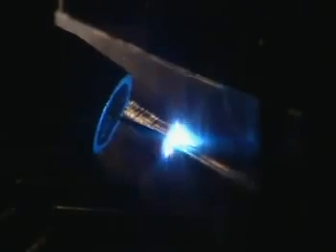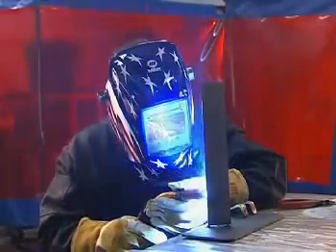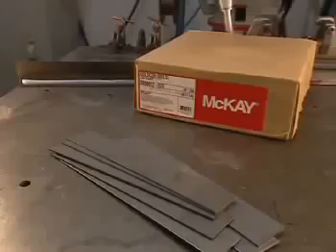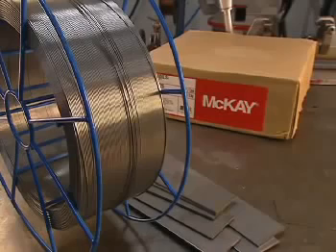In most applications, holding a shorter arc length reduces overall heat input, improves control, and increases travel speeds. This may enable superior welding on thinner materials or using the next larger diameter electrode. For example, AccuPulse permits welding steel out of position with an .052 diameter wire instead of the .045 wire commonly used, and larger diameter wires cost less and offer improved feeding performance.